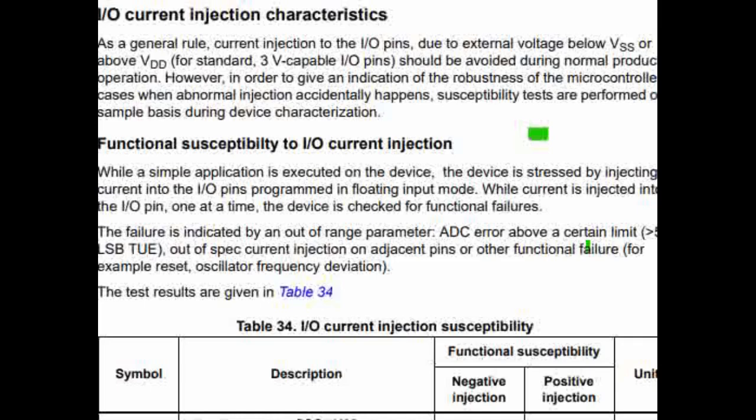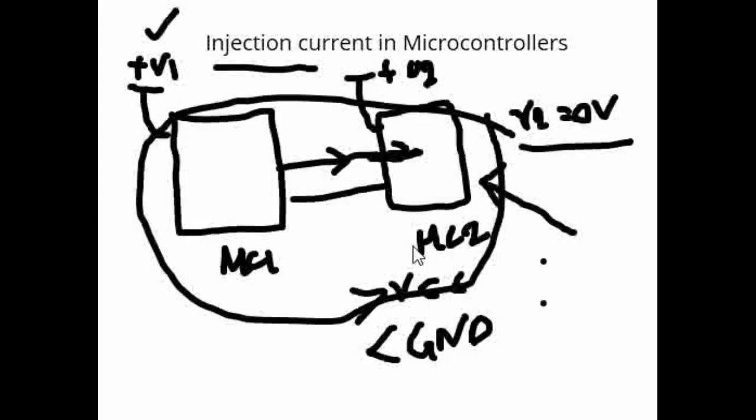One important aspect from the design side is that when we are connecting two devices, as we have shown, it is better to have a series resistor, especially on the TX side and towards the RX side, so that we limit the amount of current that goes in. This resistor should be calculated appropriately in your design.